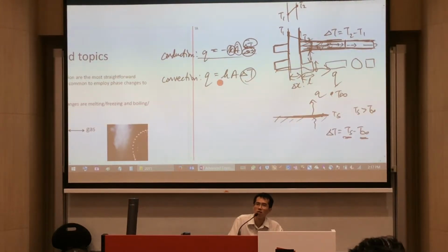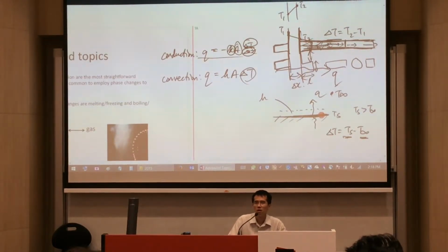That left us with the last parameter, h. h would be present if you have a boundary layer. That boundary layer would have a certain h value, the convection heat transfer coefficient, which we know is governed by a few things, for example the geometry, the surface roughness, and the fluid properties. Obviously, if you want h to be huge, we could have forced convection across the plate.